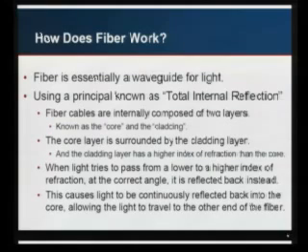What is fiber? How does it work? Fiber is basically a waveguide for light. It works on a physics principle called total internal reflection. And the way this works is the cables are actually composed of two layers. There's the core and there's the cladding that goes around that. And the cladding has a lower index of refraction than the core.